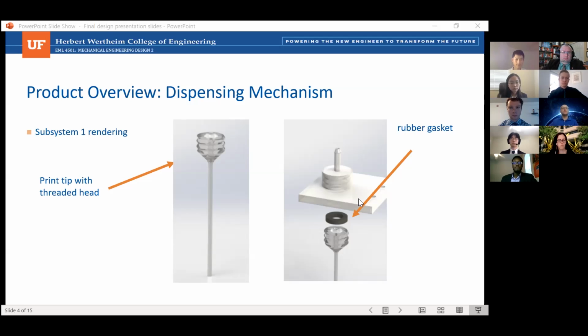The dispensing tip will be made from clear resin by stereolithography printers, and the printing needle dimensions such as length and diameter can be customized based on the customer's desirable flow rate and ink viscosity. Switching the printing head may take less than 10 seconds, therefore providing installation and replacement convenience.